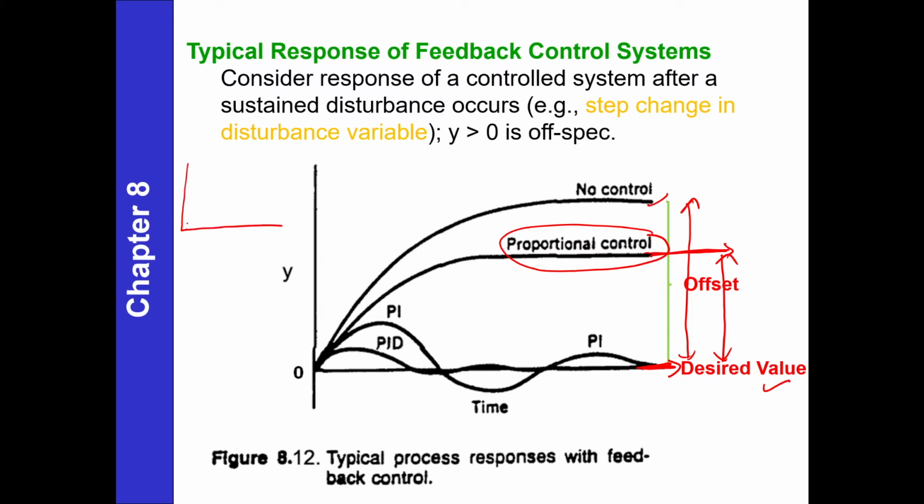From a graph, whether it is a straight line, this is called steady state, or with a sustained oscillation, it is also a steady state. It depends on the process model and on the closed loop transfer function. I don't want to talk more about that. But what I want to tell you here is that when you have proportional mode, there will be an offset. And in chapter 11, you already know how to calculate this offset from the equation.